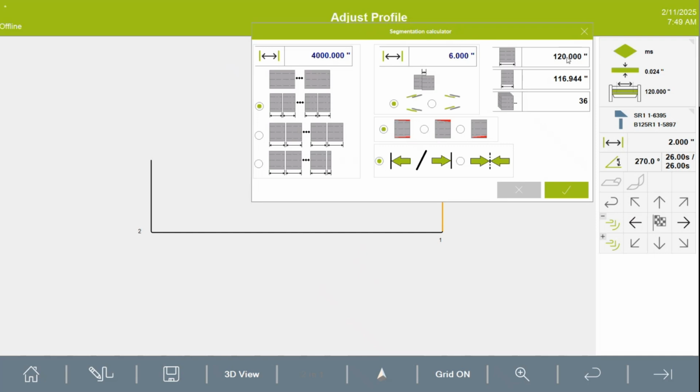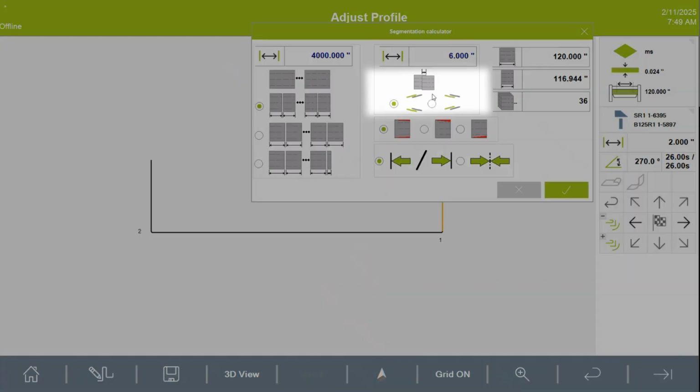Okay, and then in the middle here it says, do I want to make this thing overlap from left to right? If I click this one, I'll make the opening so that it overlaps from right to left, meaning the one on the left will sleeve into the one on the right. And if I choose this one, the one on the left will overlap the one on the right. Okay, the machine will do it for you.